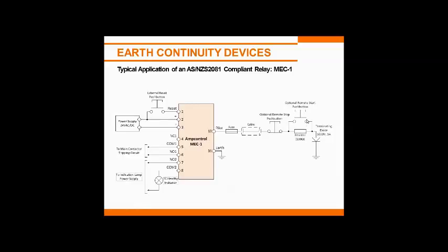And when this switch is pushed and shorts out the 100 ohm resistor, the relay then activates its output and takes up its position. That button should then be quickly released, and one of the standard's requirements is that if it's not released within 15 seconds, the system trips. And once that's tripped, you've got that 100 ohms permanently in the circuit, and the relay is now looking, say if you set it to 10 ohms, for 110 before it will trip.